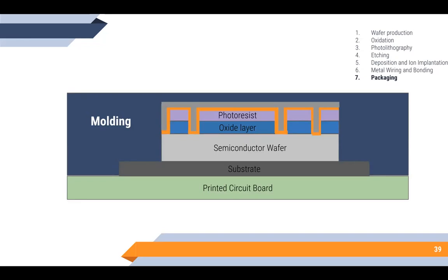This is known as packaging, and it is the last stage in manufacturing. Here, the wafer is cut into individual semiconductor chips and can be placed on a printed circuit board through chip bonding, where the contact point of the semiconductor chip is placed in relation to the contact point of the connecting substrate. This piece together now can be placed on the printed circuit board. Molding is employed on the newly formed chip, which is finishing the chip package to its desired shape.